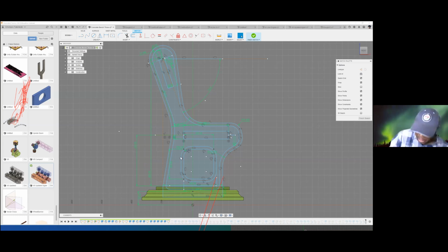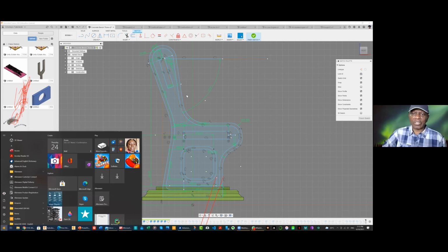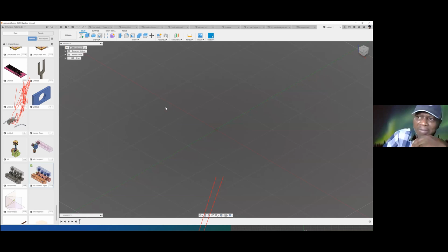Okay, so let us see how to start this. I'm just going to use this to show you the power of the sketch creation facilities in Fusion 360. So I want to start a fresh drawing. I go to my Fusion 360 and I'm going to create a fresh drawing. This thing is too dark. Well, perhaps it doesn't matter. I hope you can see it. Let us start with a horizontal line of 400. And before we do that, the first thing we do is say create sketch.